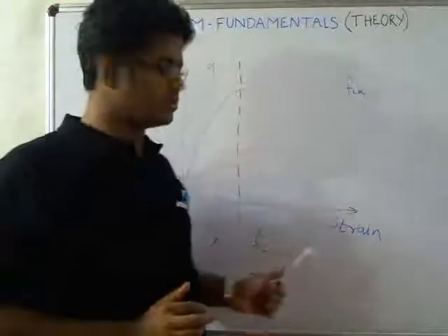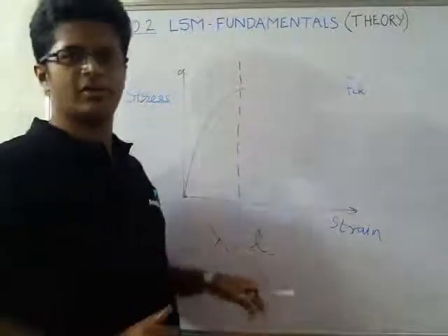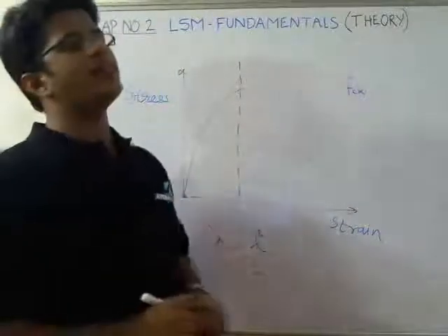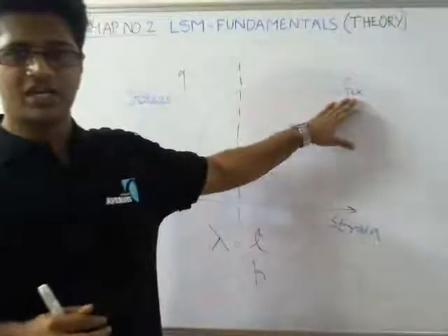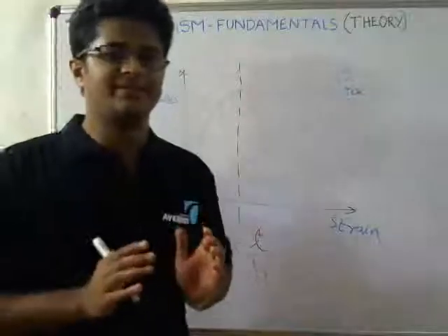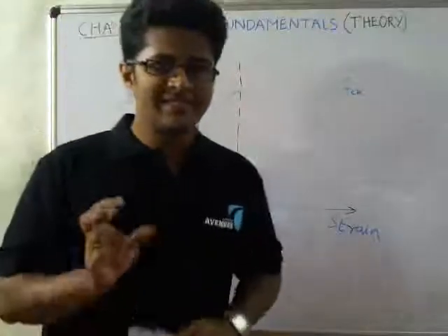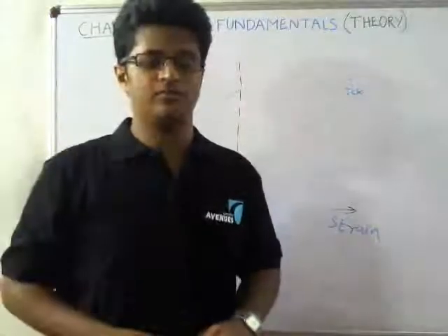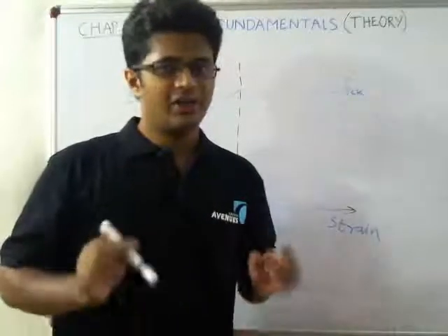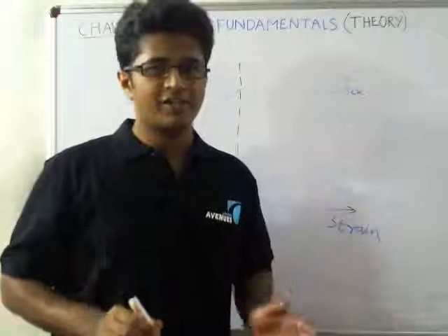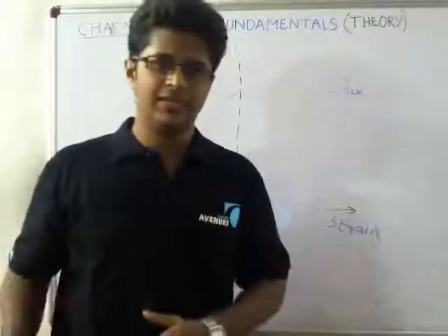Why am I mentioning this point particularly here? The reason is the FCK value which we are obtaining from the cube test. It is basically a 15 centimeter by 15 centimeter cube. But concrete is not a manufactured product unlike steel.